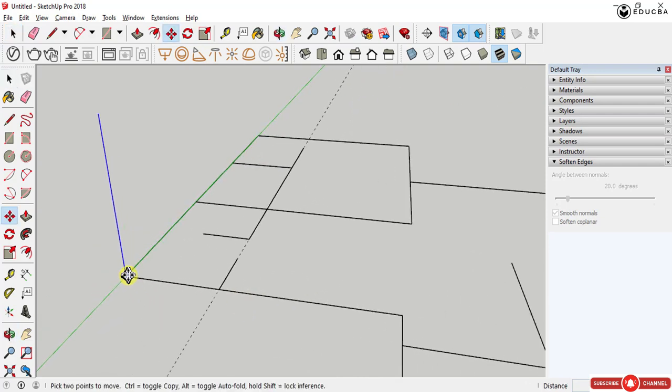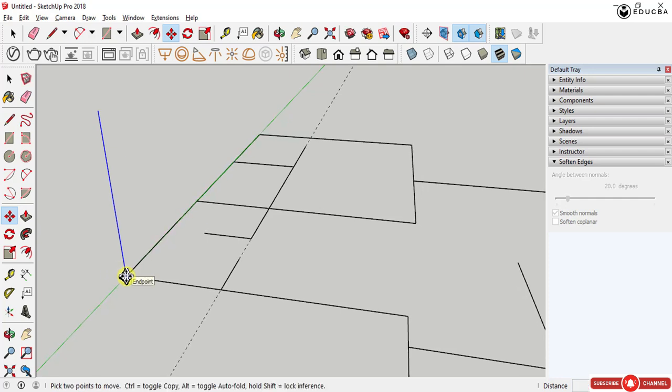I am going to now increase the wall depth by drafting another line by copying. And how you are going to copy is, let me show you again. Click the point. When you start dragging, you see it is not yet separated, but as soon as you press Ctrl, the line copies itself. And here I am going to write 230 mm, since that is going to be the exact depth of the external wall.